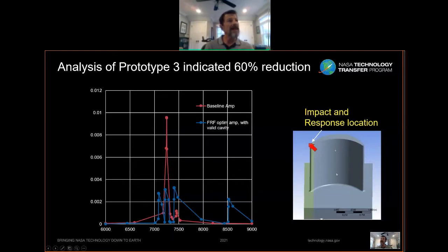Well, in your baseline blade, that's the red here. So that says when you're vibrating at 7,300 hertz approximately, when you excite the structure at that frequency, you'll get this response for your baseline blade without an absorber in it. And in comparison, when you put in this tuned mass absorber, so that original one, you'd get a response here, and then the second mode turns out to be way down there.